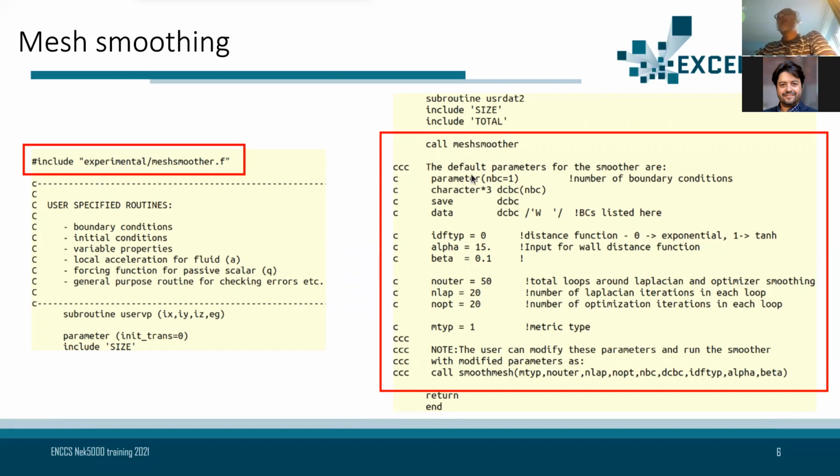The other stuff is about morphing the mesh. We were talking about usrdat2 and usrdat3. So you can now go down inside the lpt.usr file to usrdat2. And as I told you, usrdat is to move the vertices, to deform the mesh, but before all of the grid points are generated. Usrdat2 acts after the grid points are generated. And actually, that's one of the examples of how morphing works.